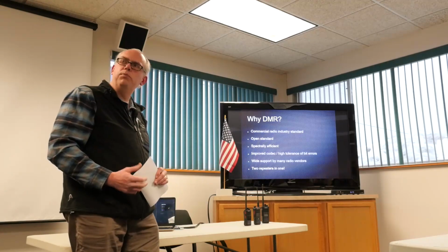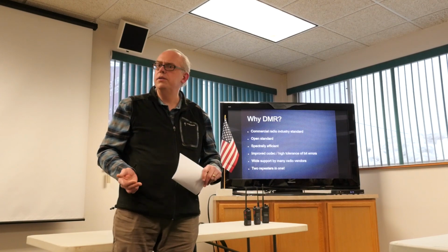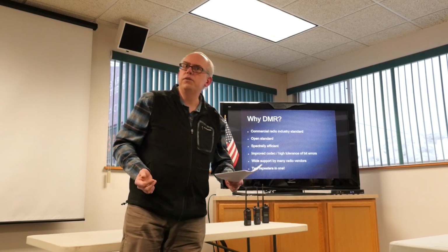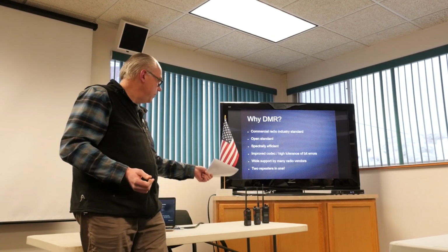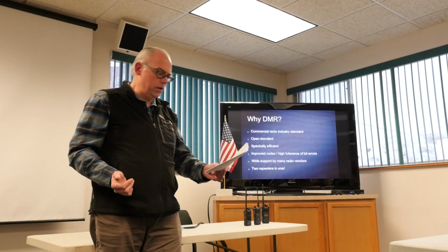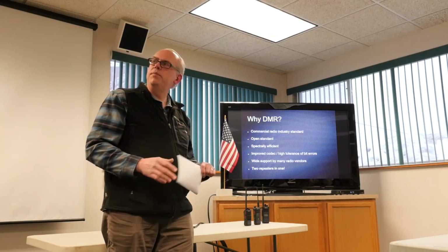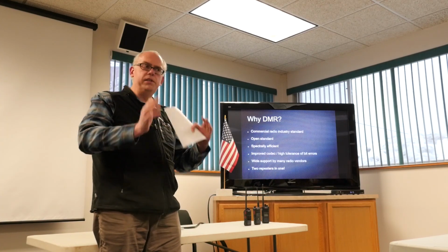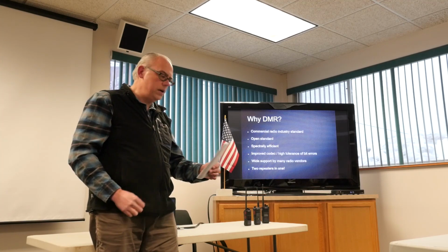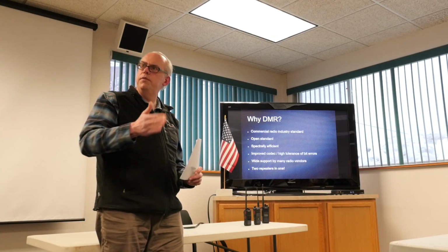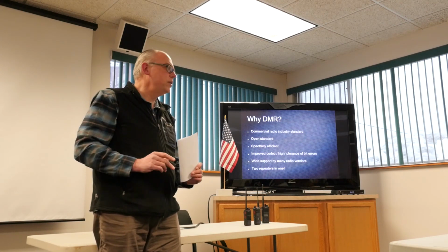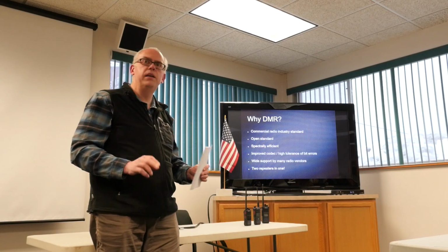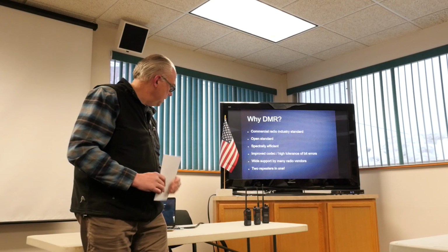Like I said, it has wide support by quite a few radio vendors. You can kick a cat and you'll probably find half a dozen different Chinese DMR radios out there. I've got a few out here on the table, and we can talk about those too. And really, the neat thing about DMR is it's two repeaters in one. When you put up a DMR repeater, because of that TDMA, or time division multiple access, you've got two separate channels. So there can be two separate digital conversations going on that DMR repeater at the same time.